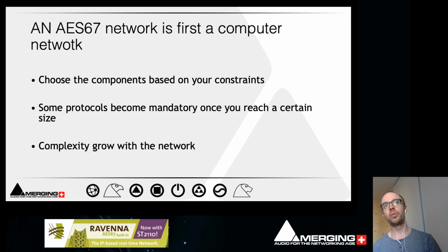But once you get to really big networks, 5, 6, 7 switches, then at some point the PTP and the ability of the switch to do PTP configuration or PTP clock correction might be useful. Always remember that complexity grows with the network, so always try to keep the network as small as possible.